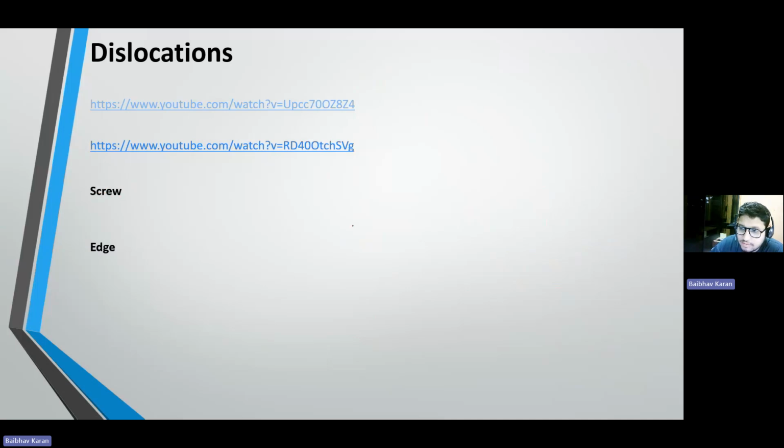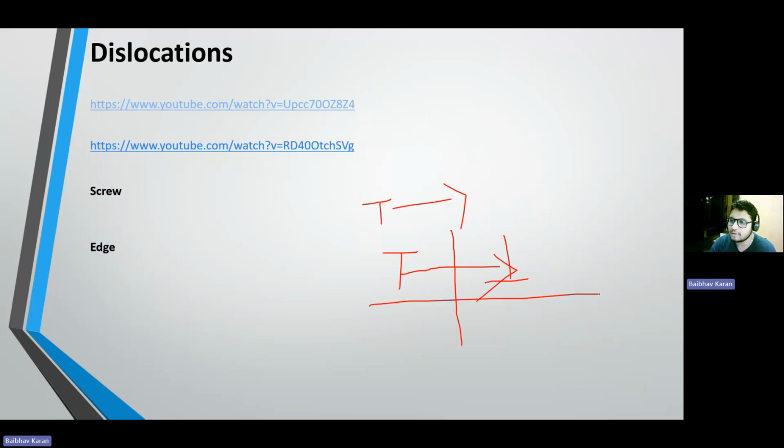It was generally observed that whenever there is a dislocation on the surface of the material, the dislocation vanishes out from the surface. It is never stable on the surface of the material. So it was assumed that there is a dislocation outside, which is just the mirror image. If this is the positive dislocation, that will be of negative, the opposite sign. So there is an attractive force between these two, and this will be attracted towards it and will move out of the sample.